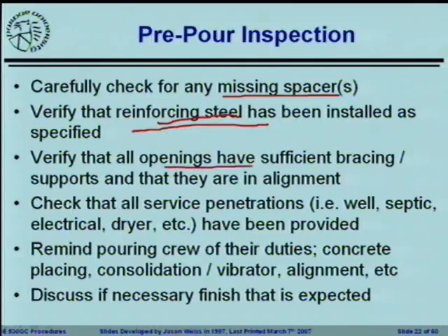All right, verify the proper openings and sufficient bracings. Make sure that everything is in alignment. All right, check surface penetrations. All right, here you might have holes. Make sure they're in the right spot. Make sure they haven't moved around.